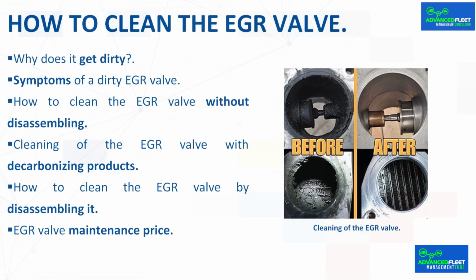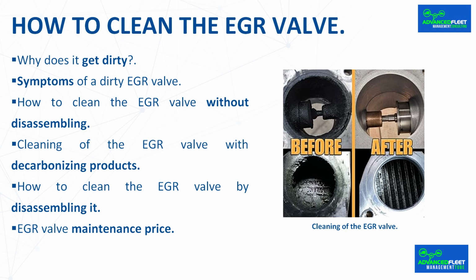How to clean the EGR valve? Why does it get dirty? The EGR valve helps reduce emissions of nitrogen oxides by recirculating a portion of the exhaust gases back into the engine. This process cools the combustion temperature, but it can also lead to the buildup of carbon and other debris, especially under conditions of low pressure and incomplete combustion.